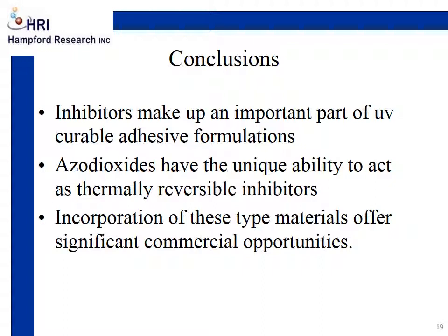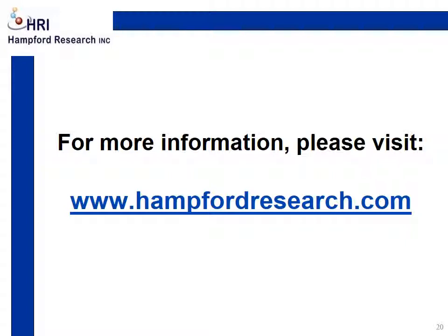So in conclusion, inhibitors make up an important part of UV curable adhesive formulations. Azo dioxides have the unique ability to act as a thermally reversible inhibitor, and the incorporation of these type materials offer significant commercial opportunities.